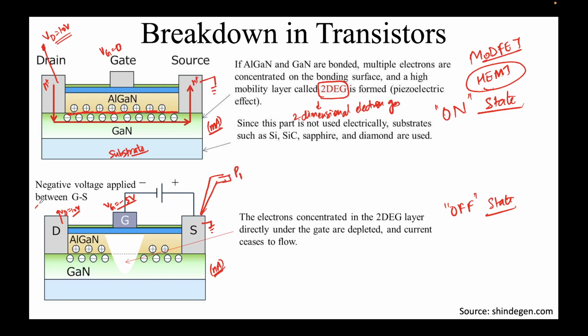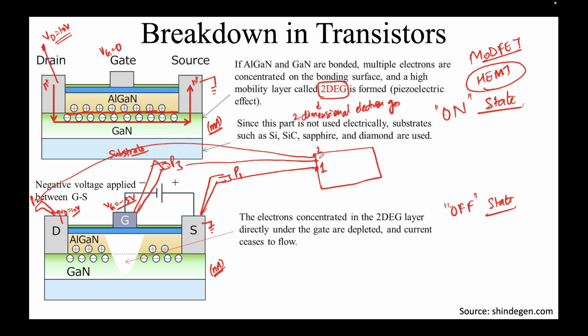I put a metal probe over here as well, over the drain, probe 2. That's how I'm providing these voltages. And the third probe is somewhere over here, probe 3. All these probes are connected in turn to a voltage source, rather what we call a source and measuring unit. So this is terminal 1, this is terminal 2, and this is terminal 3.